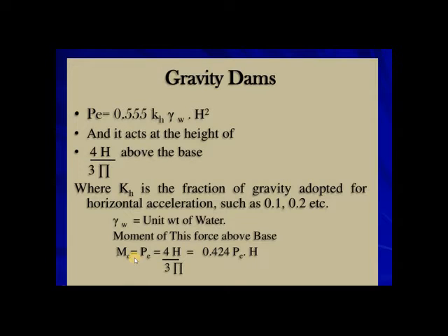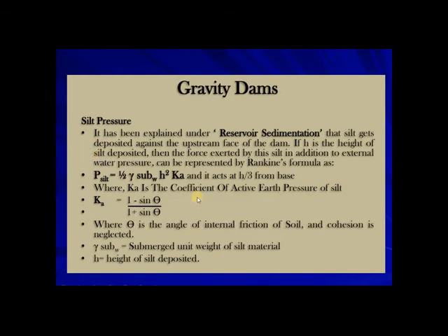So we have to calculate all the moments. Then we have to identify some moments which are supporting the dam body and some moments which are opposing the dam body, and we have to add some factor of safety in the design. So I will share a design video, then we will discuss.